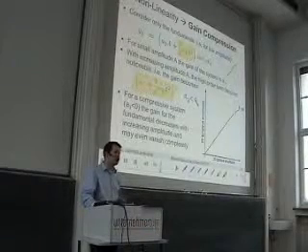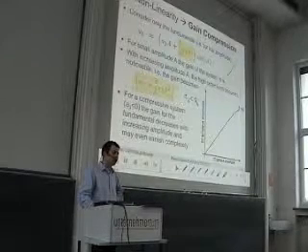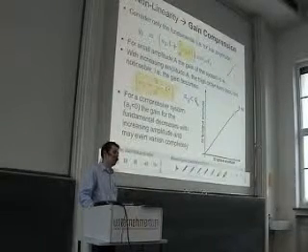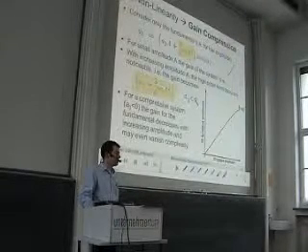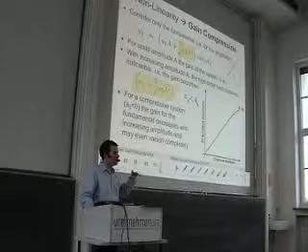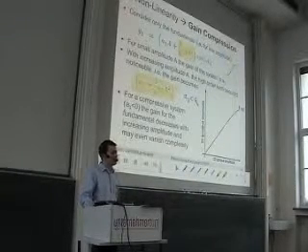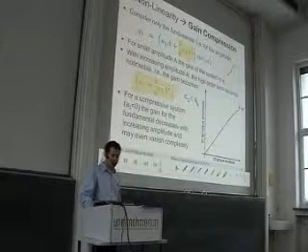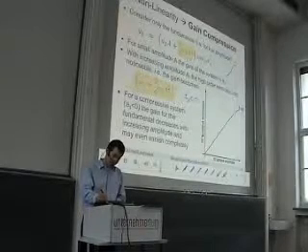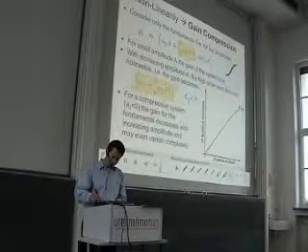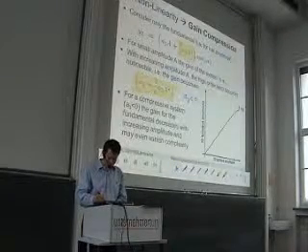And this also corresponds to what you say, that you put the signal to other frequencies. But even at the fundamental, there is impact of the nonlinearity, because the gain of the system is going down the more I increase the amplitude. This is what people call the gain compression, and it is often measured in terms of the 1 dB compression point. You can see we increase the amplitude.